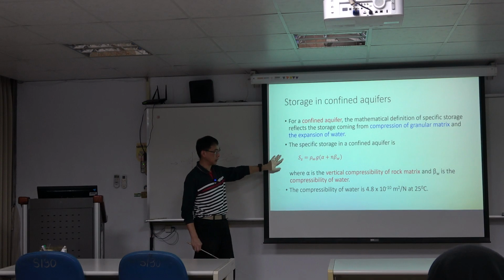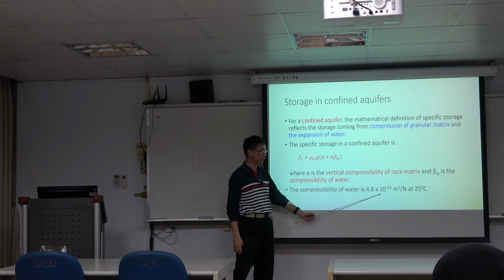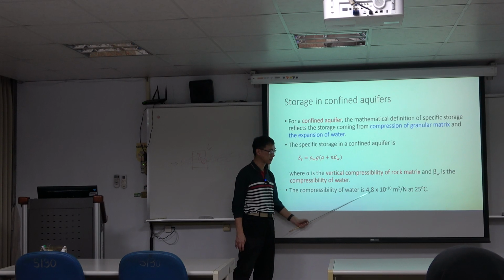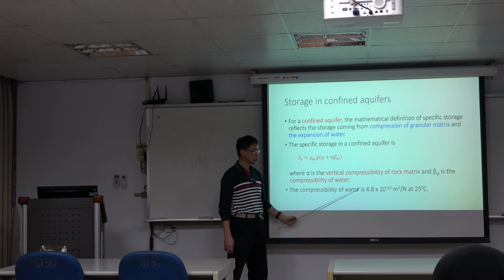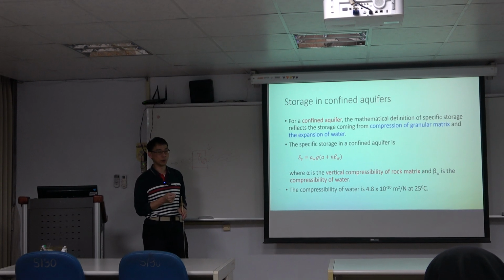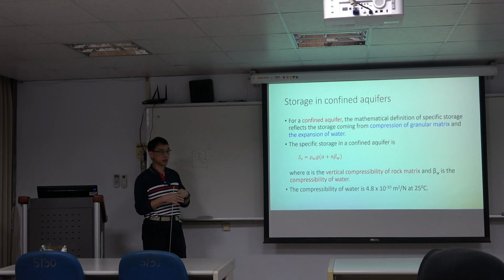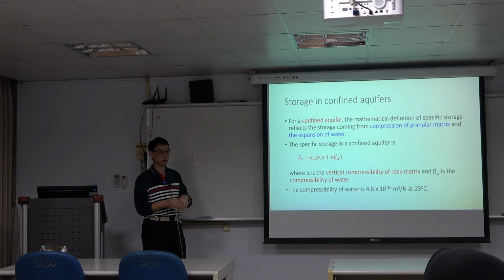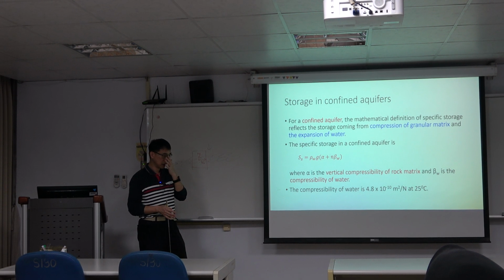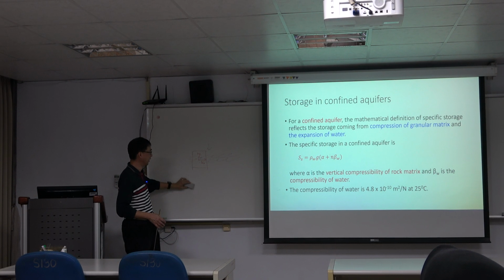Okay, yeah, like this. And you can see that the compressibility of the water is very small, the quantity is very low, 10 to the minus 10. So that means they are able to release only a very small quantity of water. That's the reason I mentioned the specific storage of the confined system: they are only able to provide a very small quantity of water. But does that match reality? Maybe not. Okay.